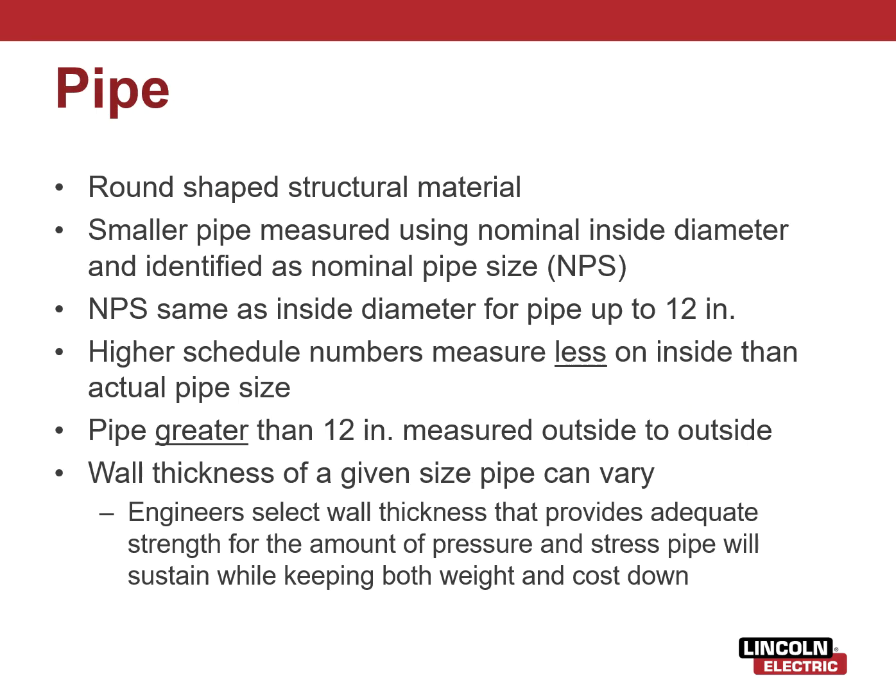Okay, pipe. So round shape, just like tubing can be, but this is structural stock now. All right. So smaller pipe is measured using nominal inside diameter and identified as nominal pipe size. So NPS, that's what NPS means. If you're ever at the hardware store asking for a pipe, and you see this NPS next to the size, that's what that means, nominal pipe size. So NPS is the same as inside diameter for pipe up to 12 inches. So this NPS is only up to 12 inches.